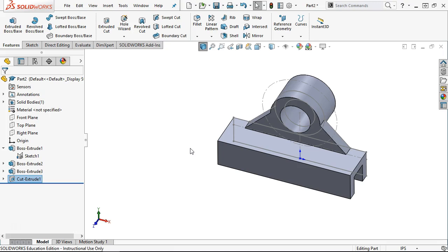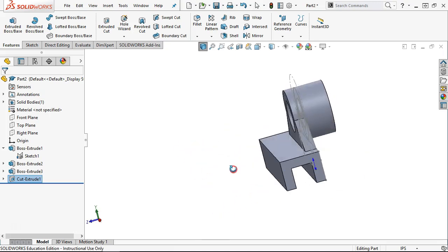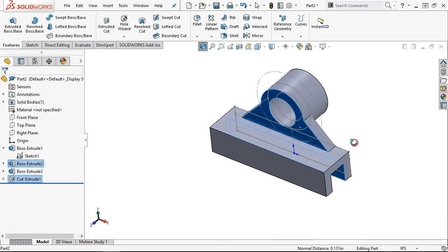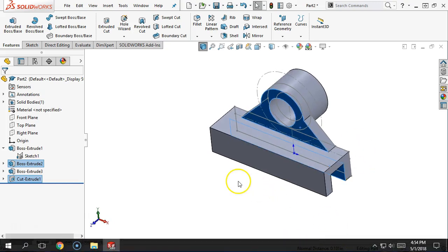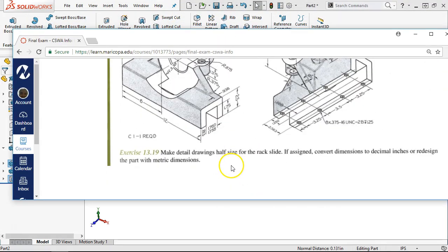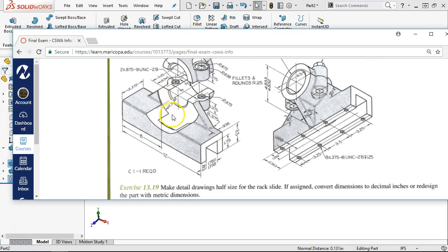All right. So, I said that this face and this face were going to end up being the cutting normal distance 0.131. So that means that this cut is going to start a little bit backwards of that face. All right, so that's a little bit of relief. That little bit of relief and the setback is going to come from that face being coplanar all the way through.